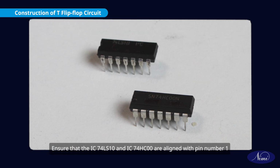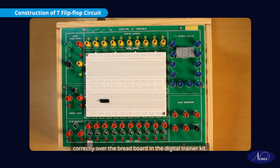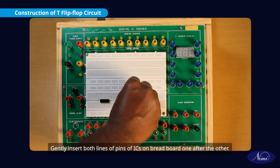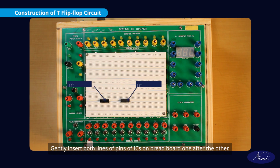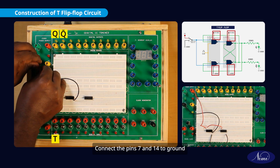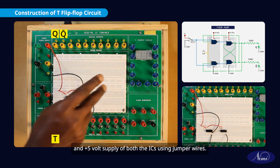Ensure that the IC 74LS10 and IC 74HC00 are aligned with pin number 1 correctly over the breadboard in the digital trainer kit. Gently insert both lines of pins of ICs on the breadboard one after the other. Be careful not to bend the pins or force them into the holes. Connect the pins 7 and 14 to ground and plus 5 volt supply of both the ICs using jumper wires.